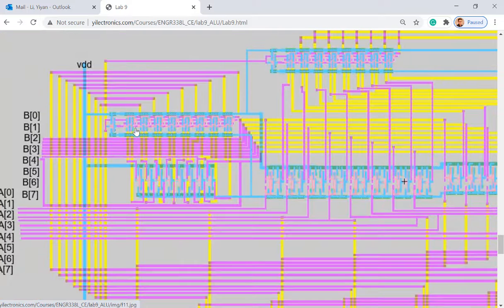I know that subcell is working, so I just grab it and put it into this layout view, and then eventually I can form a bigger layout, which is this multiplexer, and then I do a schematic check. Boom, probably only 2 errors. Easy to fix, just 2 errors. I just find out and fix it. Okay, then the multiplexer is done. So I know the multiplexer is ready. The multiplexer here is one subcell. I know it's ready to use. It's just sitting in the library.